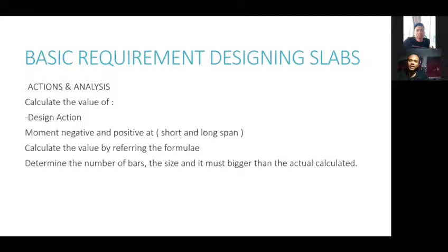Basic requirements for designing slab. Action and analysis. Calculate the value of design action, moment negative and positive at short and long span. Calculate the values by referring to the formula. Determine the number of bars and the size, which must be larger than the actual calculated area.